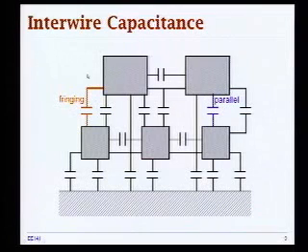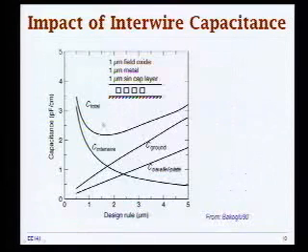And second, as you go up higher through the metal stacks, you observe that your capacitance to ground is reduced, because you're getting farther away from dielectric, and you have also a lot of wires around that you terminate your electric fields to. And where is this all going with technology scaling?